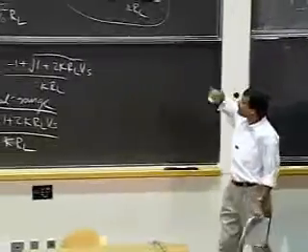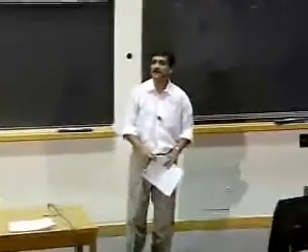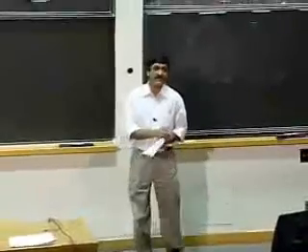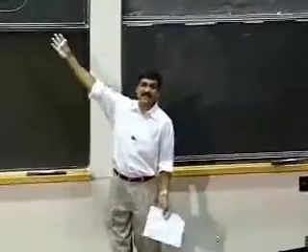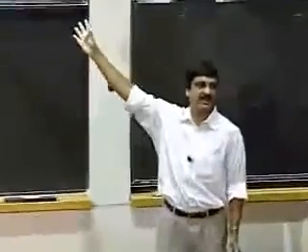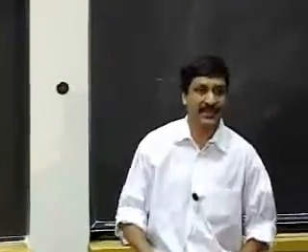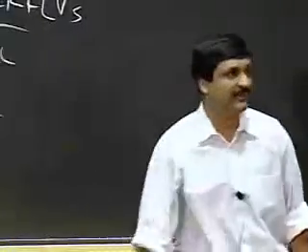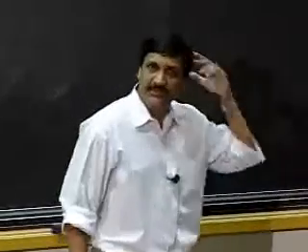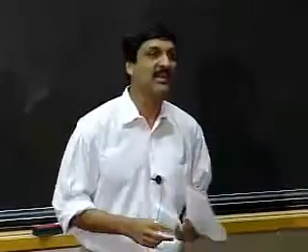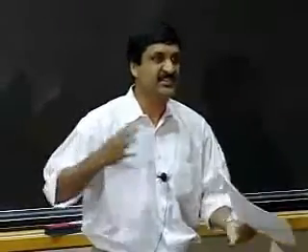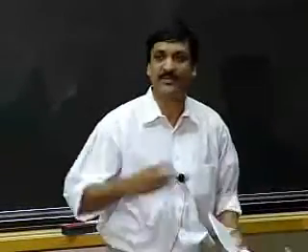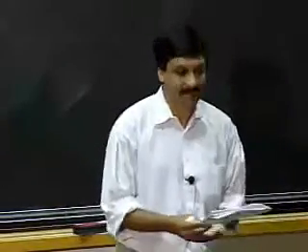Out here, I began by looking at the transfer function, the V0 versus Vi curve, and used that to drive the intuition behind how we calculated the bounding regions. Okay? You can do the same kind of analysis intuitively looking at yet another curve or another set of graphs that you are familiar with, and that's a load line characteristic. And it's interesting to get two interpretations, and you can use whichever one you feel comfortable with.